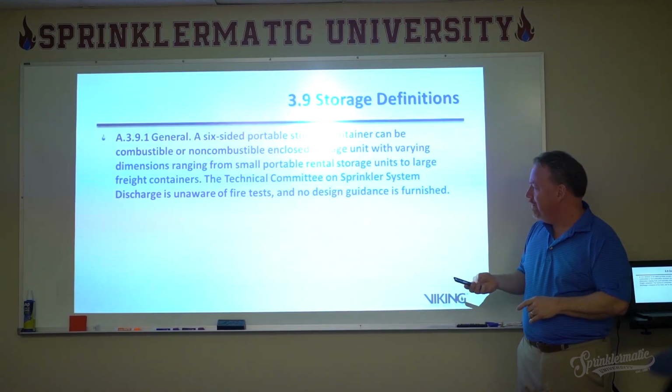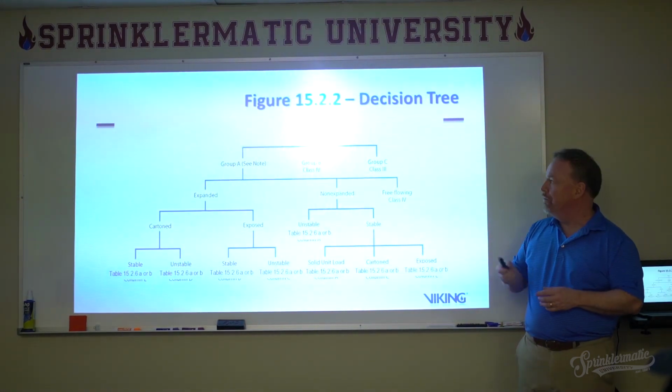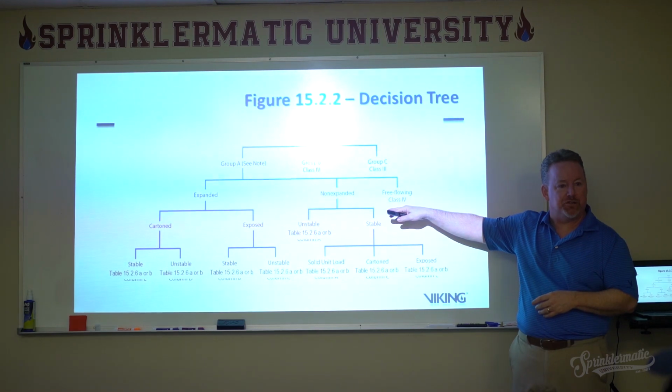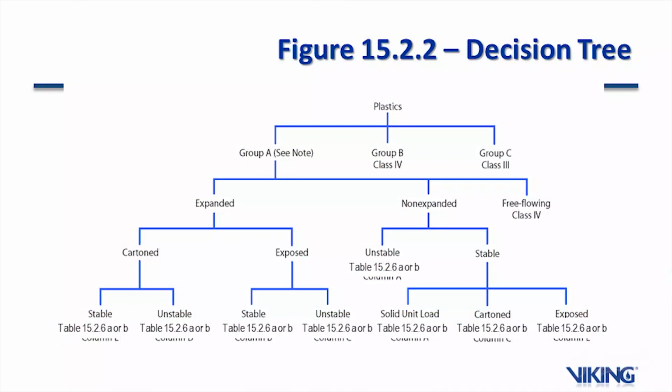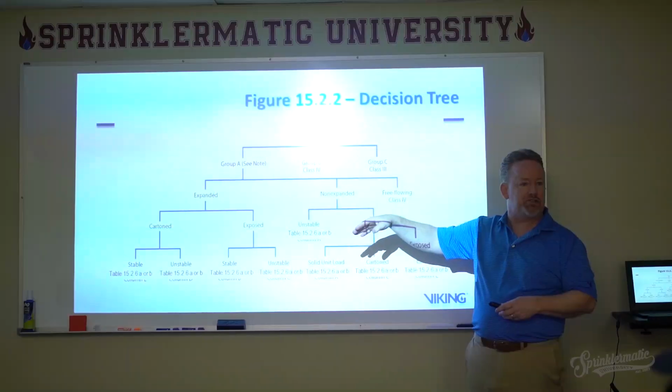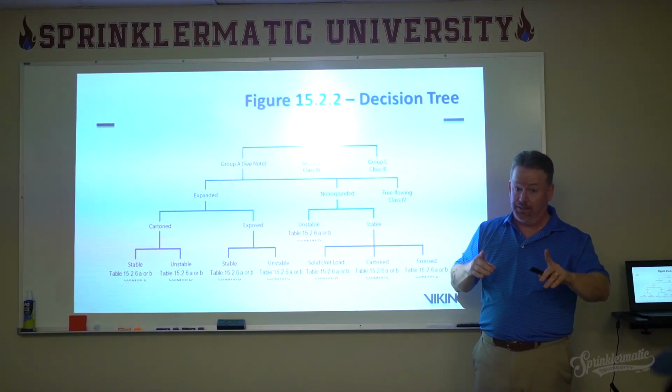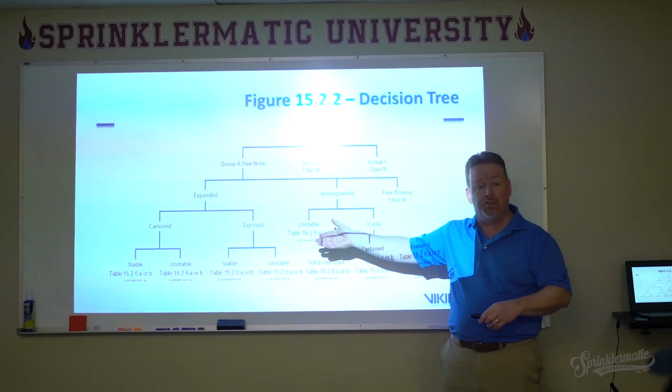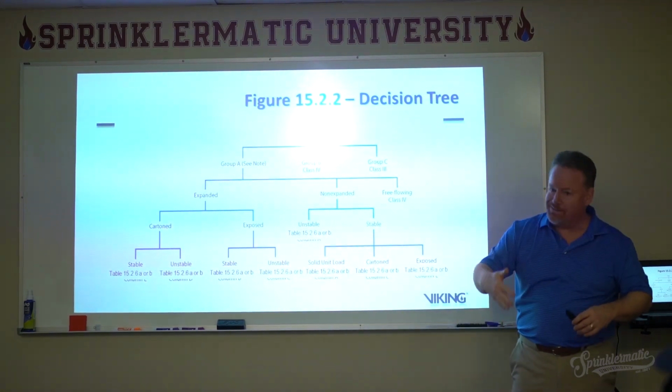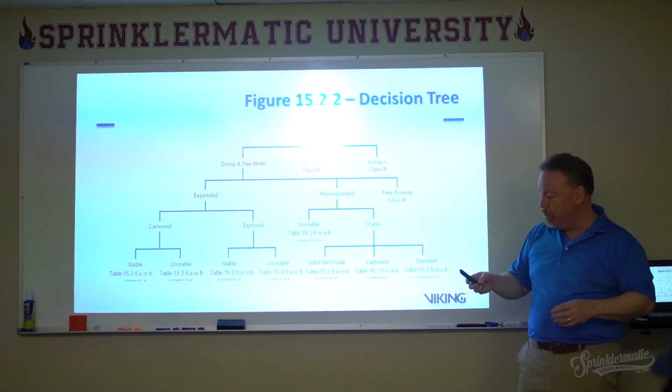However, you're kind of not on your own, because remember, you go back to this decision tree, which takes you down through, well, what's the worst thing you could possibly store in there legally? Okay, legally, what's the worst thing you could put in there? Is a Group A plastic, right? Because you can't put gasoline or anything like that in there. So it's a Group A plastic.